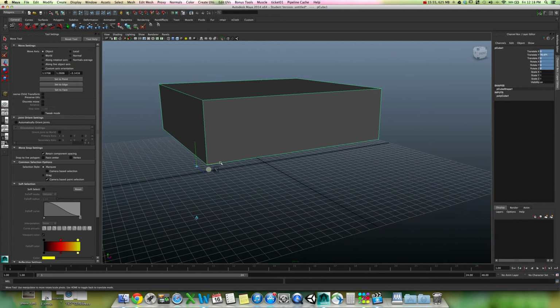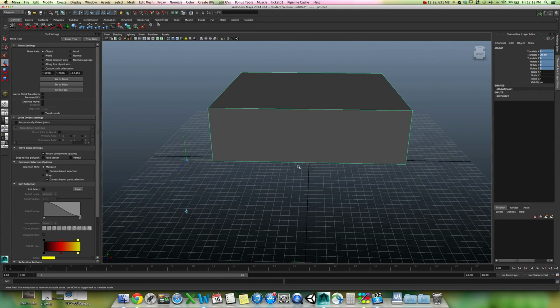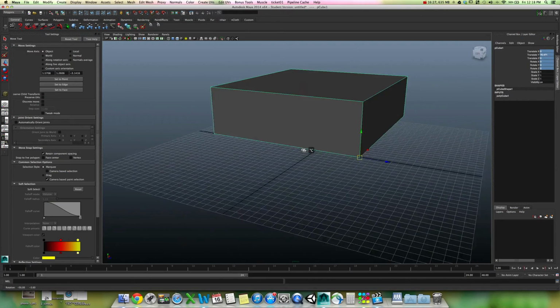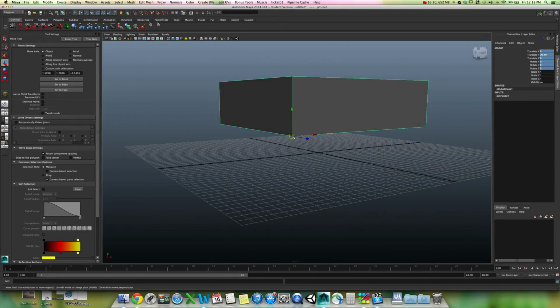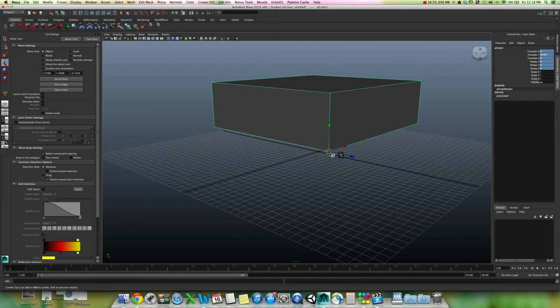All right, we don't need to do any of that. That's ridiculous. What we're going to use is what's called a snap. And a snap will snap this to any type of point or point in space of our choosing. In this case, we are going to hold the V key down. The V key down is a snap to a vertex or any point in space that is defined. So now all I have to do is click and drag and boom. Now it'll snap to any of these points. And let go. Now we leave our function left arrow or insert, which is our pivot mode. And we can see that we have a point in space where we snapped this that's actually useful now.